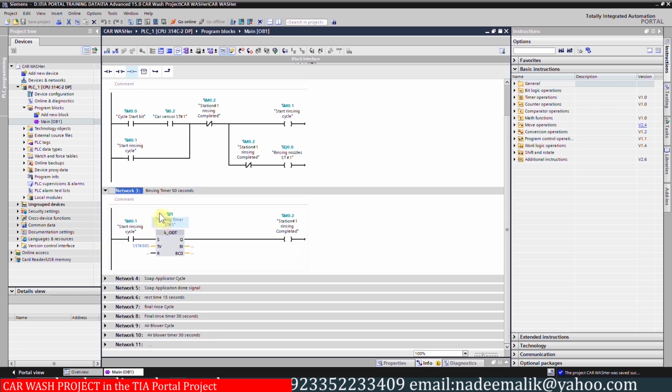In network number 3, we have a rinsing timer. When this bit M0.1, start rinsing cycle, is on, it will start this timer T1, and once the 50 seconds are over, it will turn on the station number 1 rinsing completed bit, which is M0.2. We have inserted the normally closed contact of the M0.2 bit here, so once the 50 seconds are over, this contact will open and turn off the Q0.0 output for the rinsing nozzles, closing the nozzles and stopping the water on the car body.